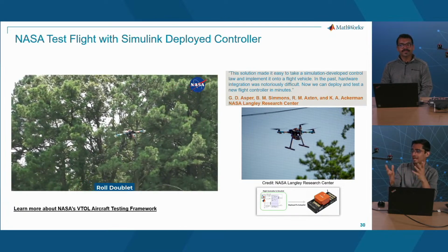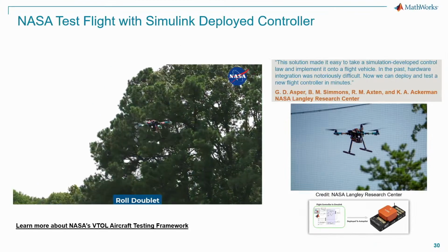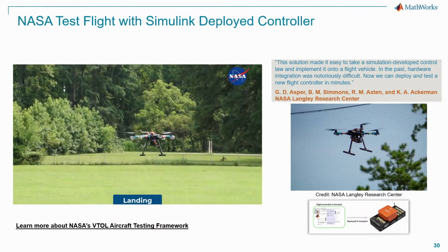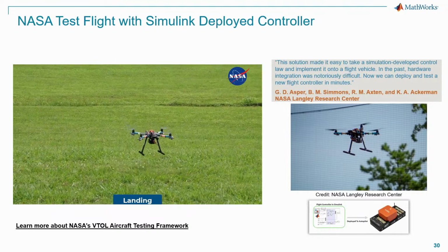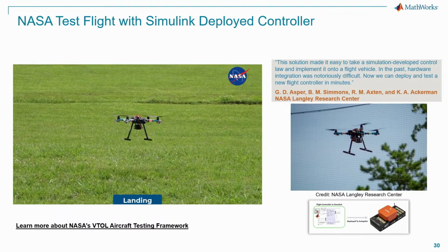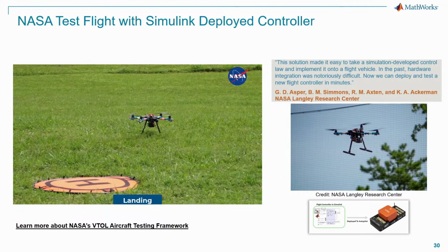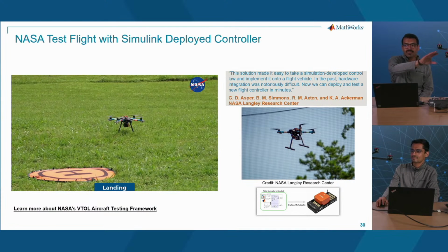But what NASA did outside the lab environment, and actually went and flew the drone, what was that they did? Yeah, they used the same process. They built their controller, they had an idea of what their plant looks like, and they tested everything out in a lab setting where it's reading data in Simulink. Then they tested it out connected on a 3 degree of freedom rig, and then they went and did the same test with actual propellers outside.